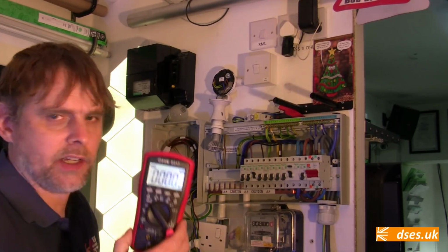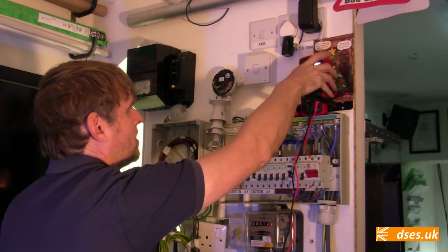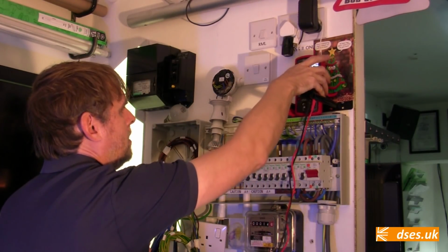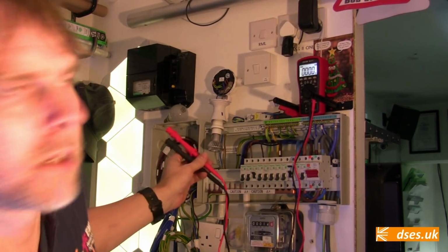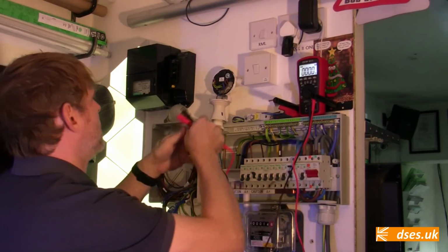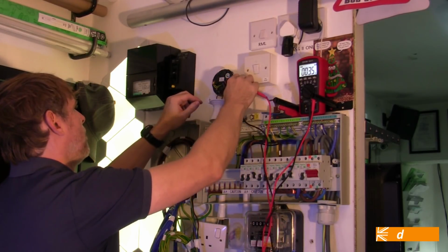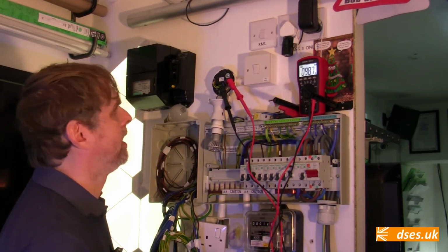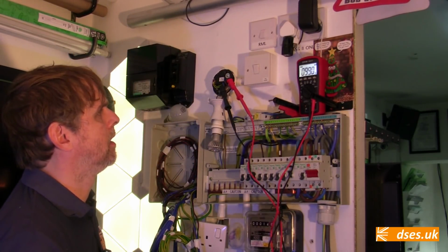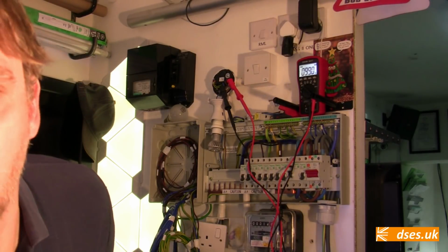Let's run with the TIS E217 then, because that gave us the most impressive reading, and it also has that nice backlit display which hopefully shows up on camera okay, kind of. So I'm going to connect that, and of course as I connect it the lamp extinguishes and we get this reading of currently 98.9 volts, 99 volts. Can the camera see that? I think it can see it.